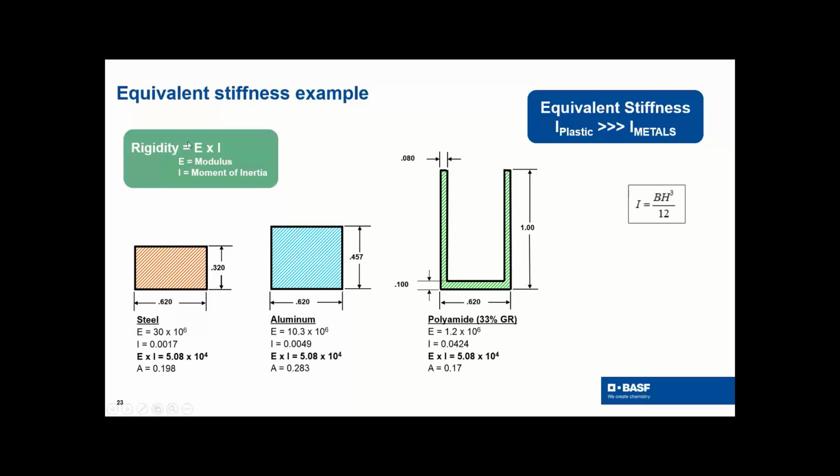So there's two things in stiffness. One, everybody knows the material has a stiffness, and that's your modulus, if you will, and that's on our data sheet, and again for room temperature. But the other stiffness is a geometry stiffness, and if it's bending, it's the moment of inertia. For a rectangular section, it's going to be I equals B, this base, times your height cubed, divided by 12. So really, if you want to increase I, since H is cubed, that's the dimension you want to change, and that's what we did for the aluminum.